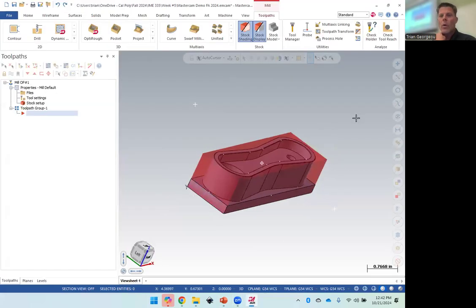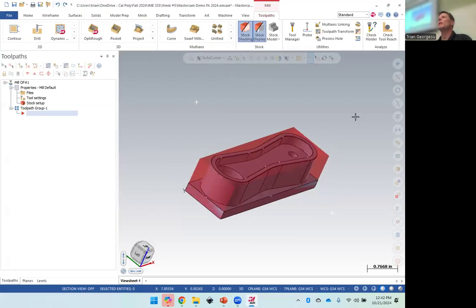So what toolpaths do you think I need to do in order to plan this, everybody? I want to hear it from you. What do you think I'm going to do first? Face mill, that's a good idea. So we're going to face it to the right height. What do you think we're going to do second? There can be multiple right answers. We could drill. We could contour. Yeah. So when you say end mill, we could contour the outside, right? Where else do we have to contour? The inside, right? We'll contour the inside.